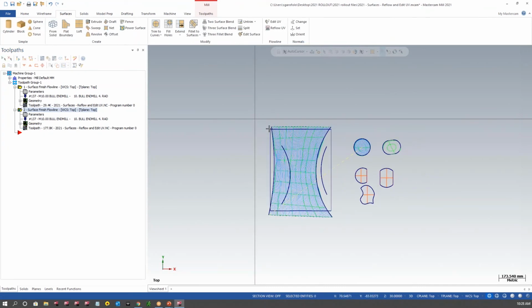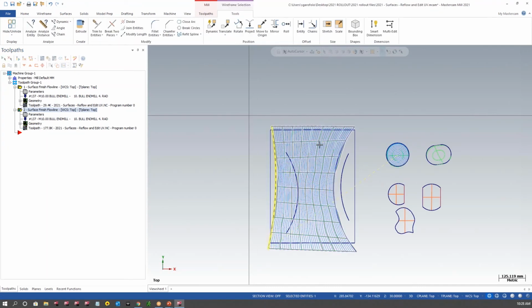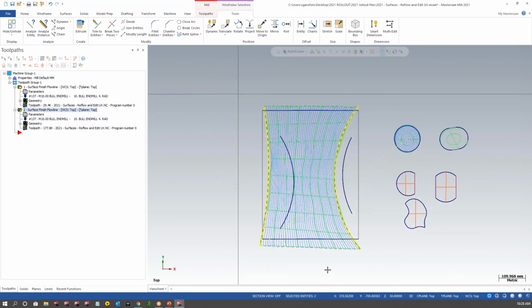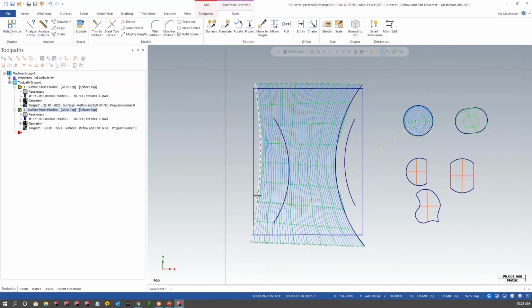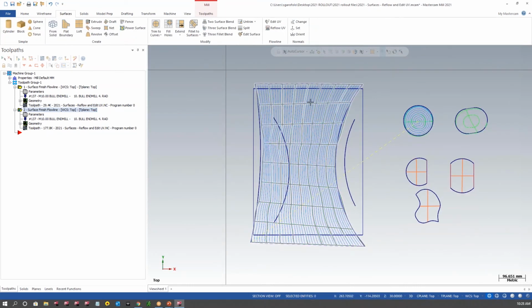So a blend toolpath, if you're not familiar with it, will always blend between two pieces of wireframe geometry. You could say cut this surface, but I want you to cut this shape as you're over towards this line. As you move to the right, I want you to start cutting this shape. And that's literally exactly what we have here. We have a nice blend toolpath that blends between those two shapes as it goes ahead and cuts that surface. So if you're not too familiar with blend, but you're a fan of flowline, this might be a good option for you to try out.